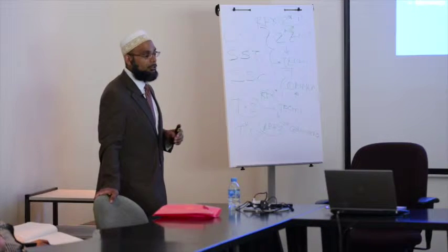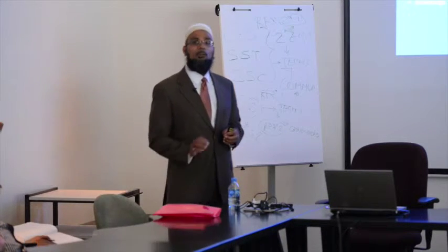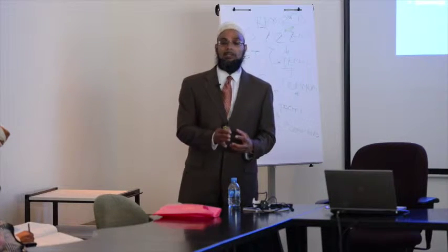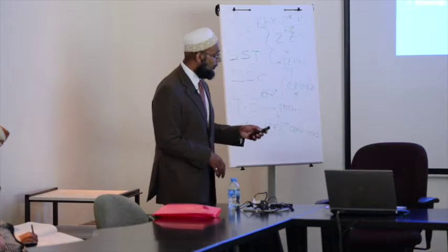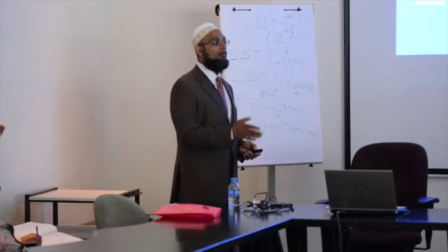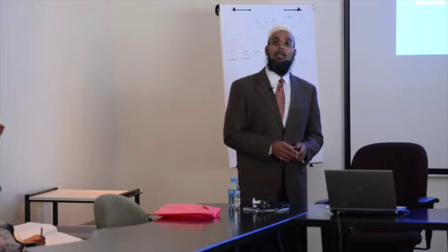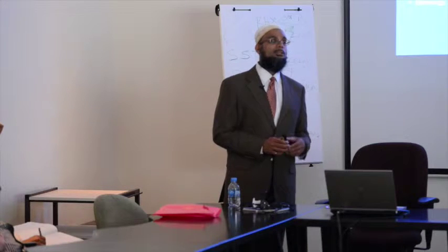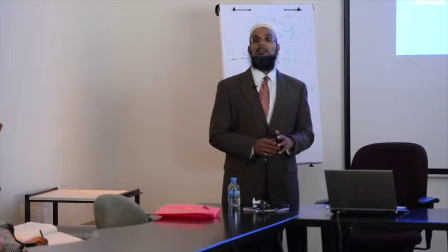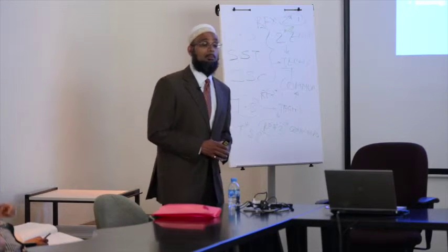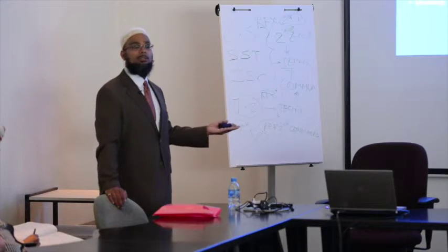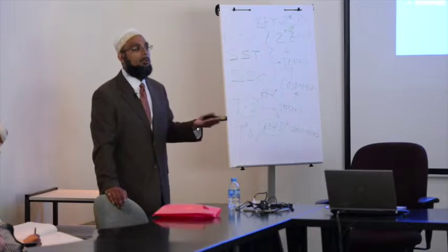And the next challenge, the biggest challenge I see, is the fluid selection. Which acid do I use? Which is the best acid for my formation? The choices are quite a few, and they depend on mineralogy, temperature, rock type, and quite a few other variables. But unfortunately, the decision for selection of acid is only made by one variable, which is the price, which unfortunately can change between the lowest cost acid to the highest cost by maybe a factor of 2, 3, 4, right?